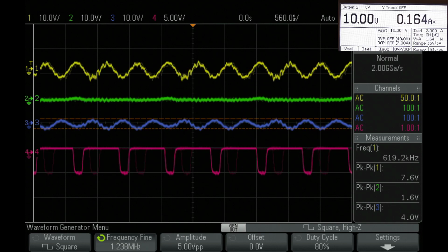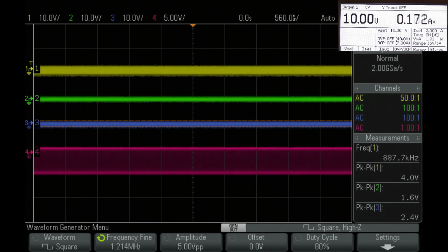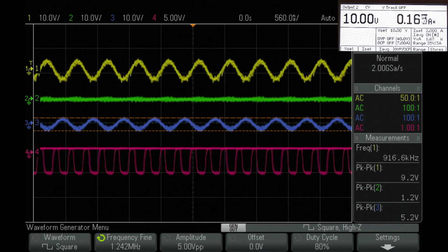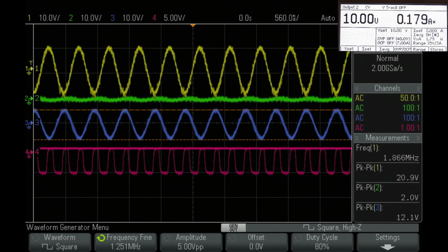That means we require much more power, 1.8 watt. As you can see, I have 20.9 volt peak to peak. However, I cannot change that anymore because I'm already at the lowest value I can do here from a duty cycle point of view for an inverted signal.